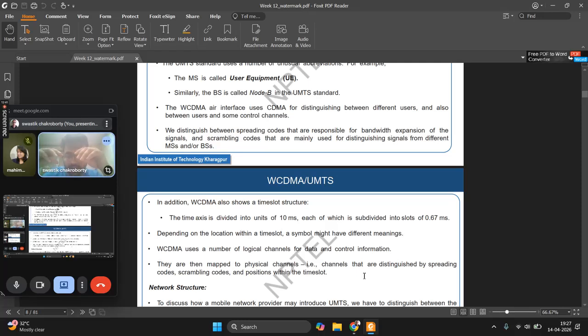The header gives the agent which is receiving these packets an idea of what is about to come, whether it is a data frame or a control frame. And then of course there is the payload, or the data or control instruction or whatever is needed to be communicated. In the tail there is some redundancy check, the CRC, cyclic redundancy check, which will ensure whether what you have transmitted is correct or not, whether some bits have been corrupted. And finally there will be a terminator which will flag the termination of that particular frame. So the same bit in different portions of the time slot will have different meanings.